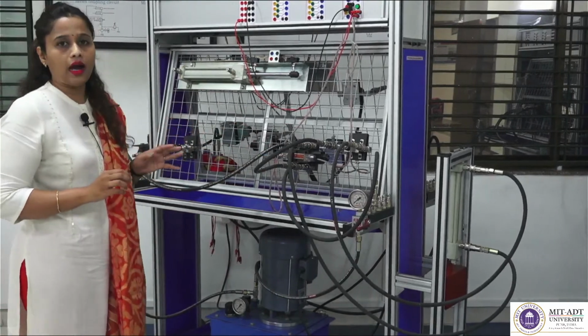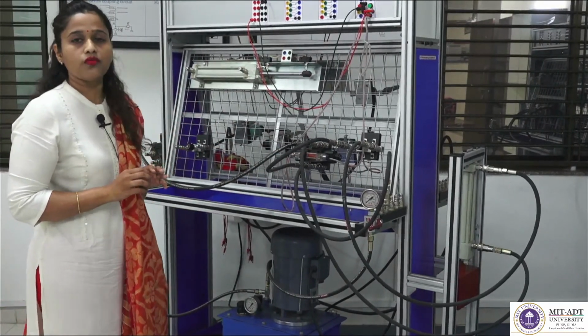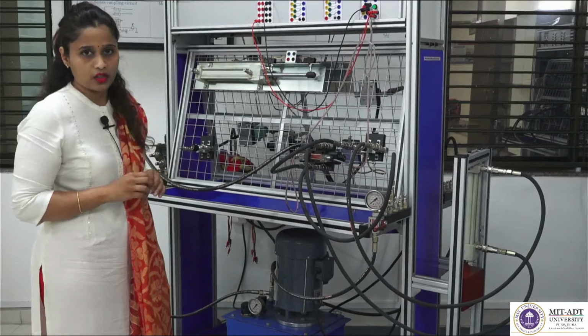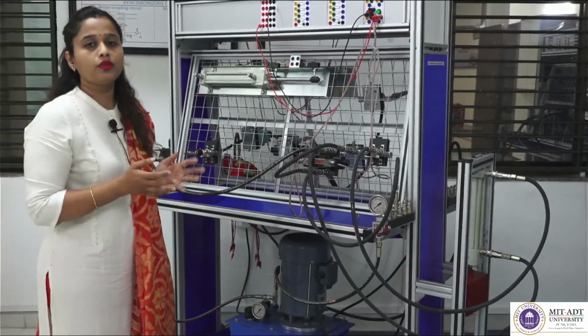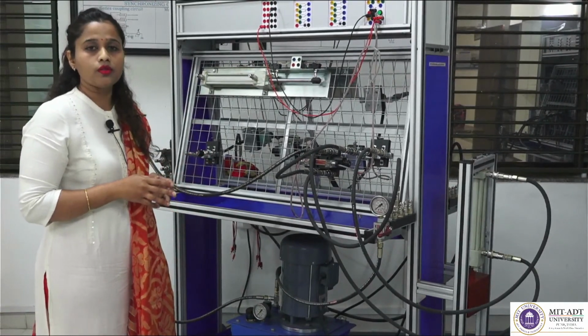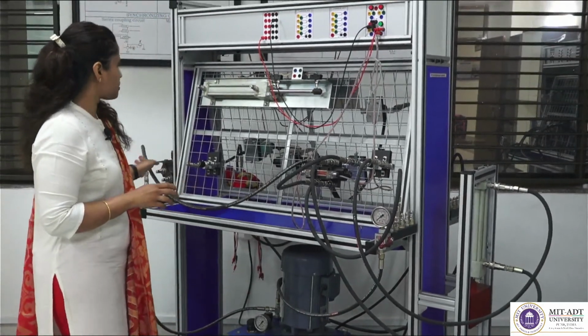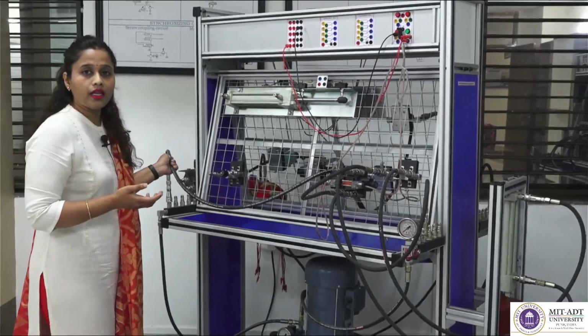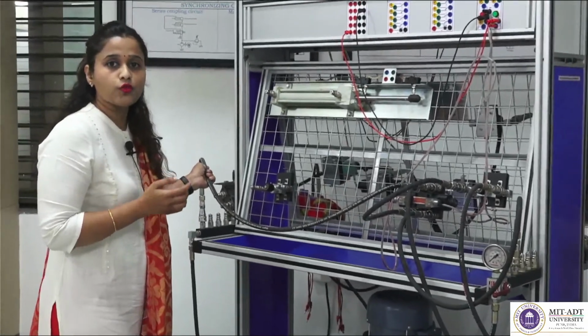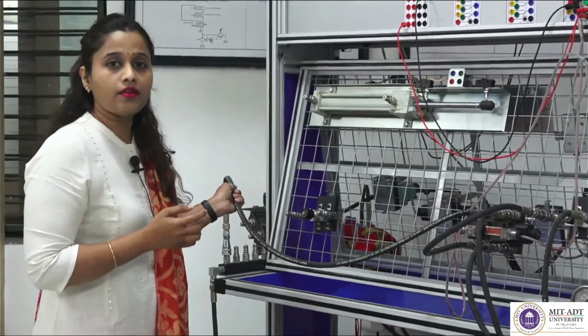For moving it down, for vertical cylinders, we always use a counterbalance valve, or option to that counterbalance valve is we can use pilot operated check valve also. So, quickly just see over here, or else in order to slow down the speed, we can use FCVs also.